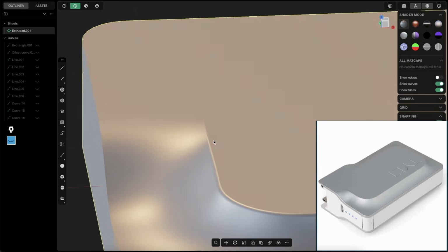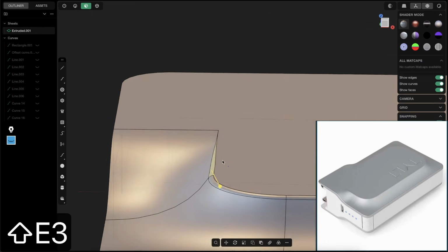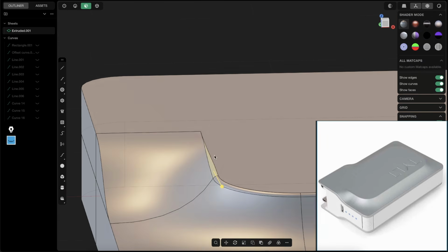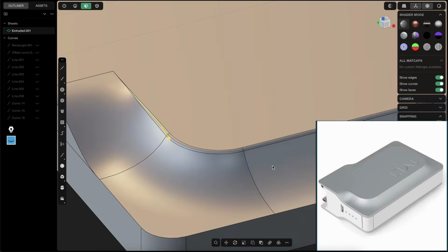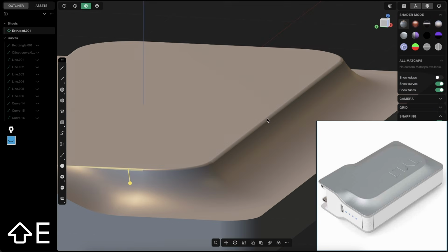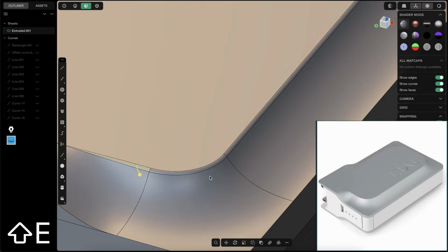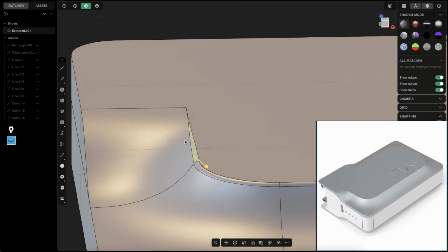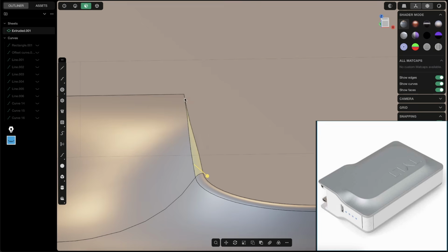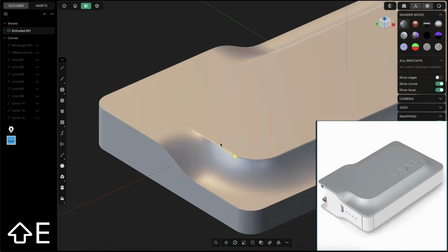But you see, this fillet is not clean, right? Because it's a triangular fillet. Why do all of those other fillets look so good? Because they are always 4-sided and proportional, right? But this one is just a triangle and it's ending in just one point, and we don't want that.